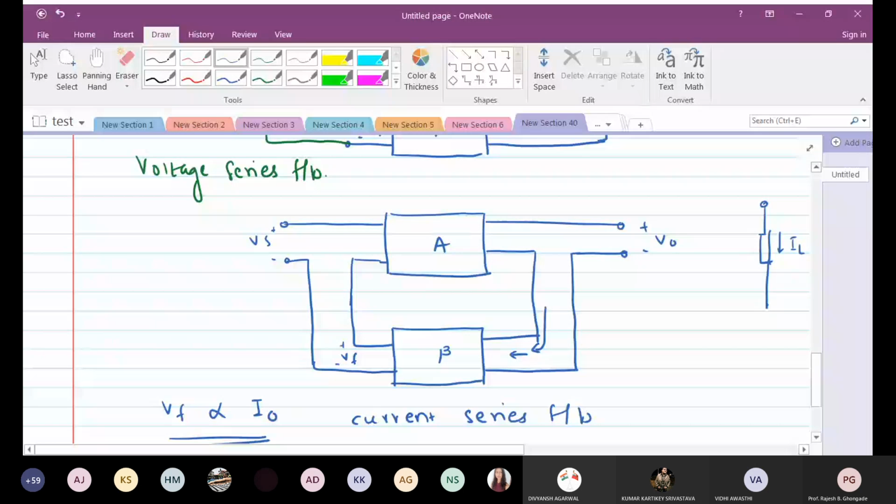I will have a very small resistor here and simply monitor the voltage across it. The current will be the same because this value is very, very small compared to the load. Again it is a potential divider itself. This VA, or whatever you would like to call it, will be proportional to current.